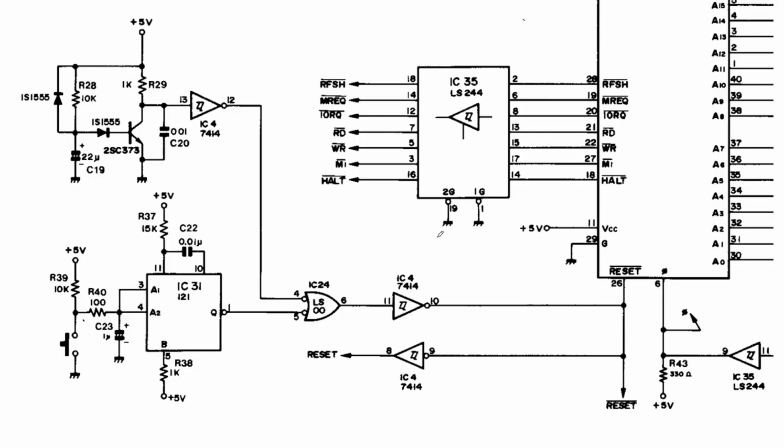So let's see. If we look at the schematics, the reset pin of the CPU is this here, pin 26, and reset is active low. And that's what we are seeing. We are seeing an active low level at pin 26, and that's why the CPU is constantly in reset mode and doing nothing. If we trace this line here, it goes through an inverter. IC4 here, it has, I think, 6 inverter gates. And after that inverter, it comes from this OR gate.